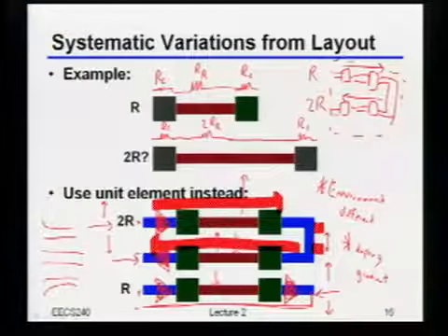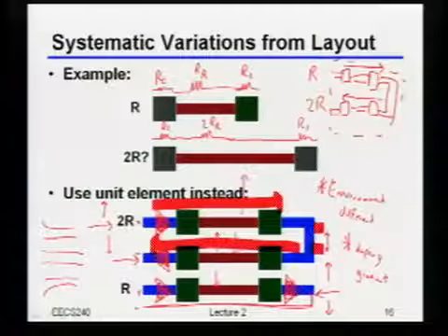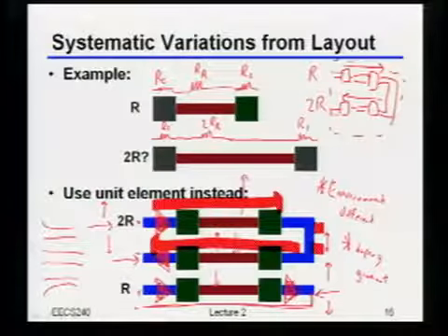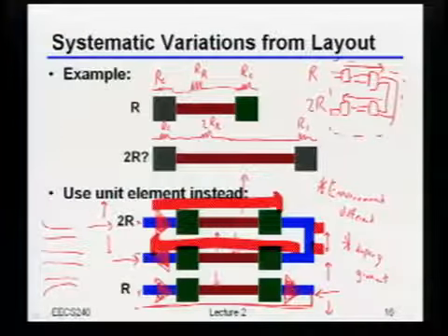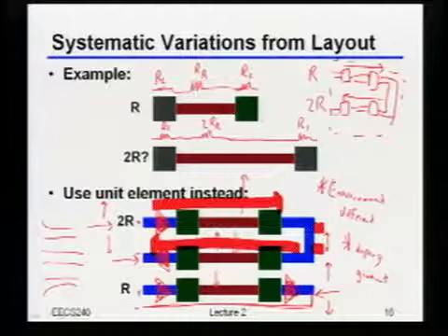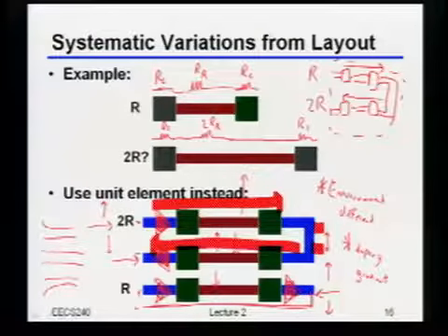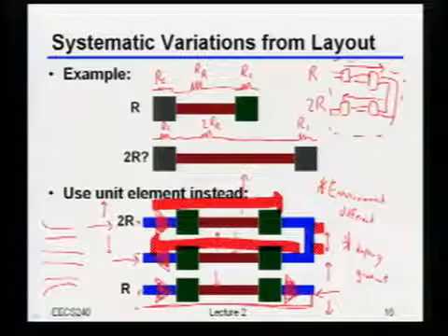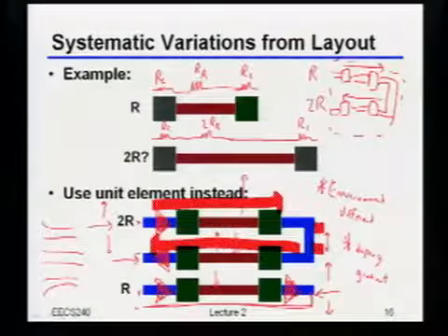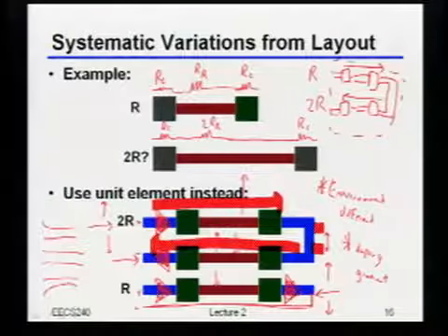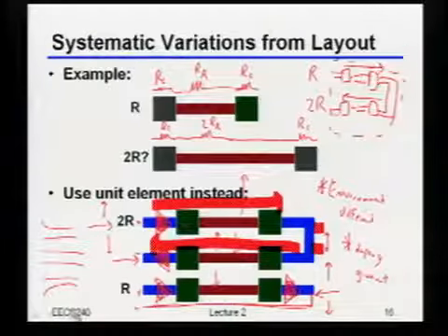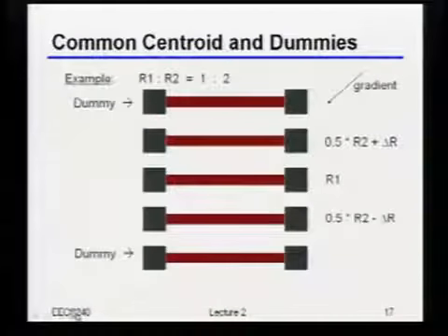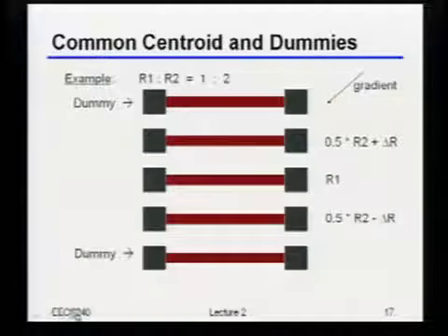Okay, so again, just to be clear, when you do real layouts in analog, you should do the same thing actually for MOSFETs as well. Anytime I build MOSFETs that I want to match, I make sure there's always actually two physical transistors, maybe with a shared drain, but I make sure there's actually two physical transistors there, just so that I don't make this stupid mistake.